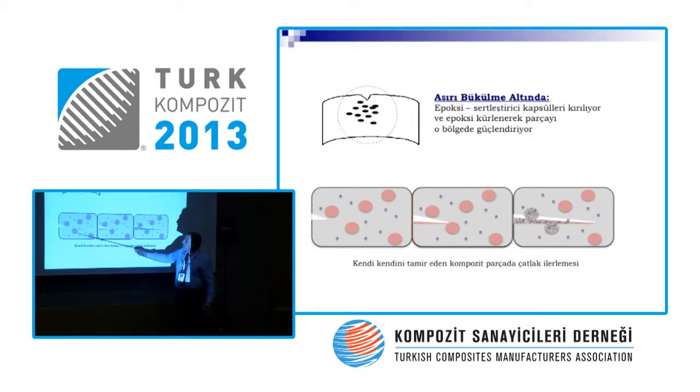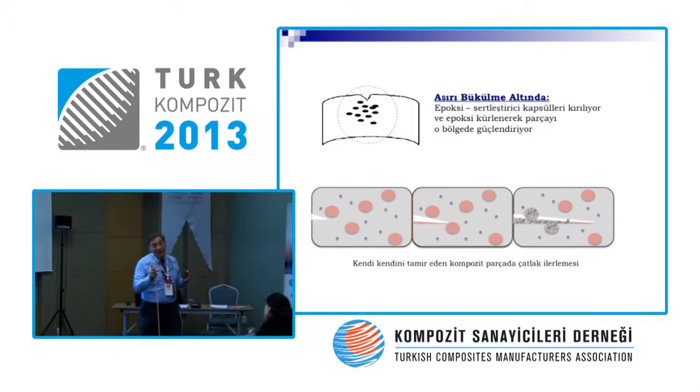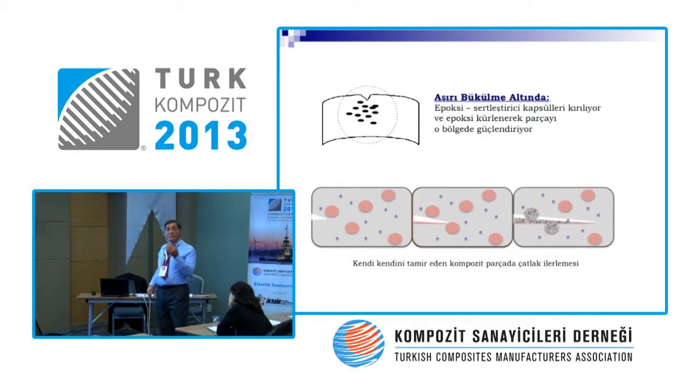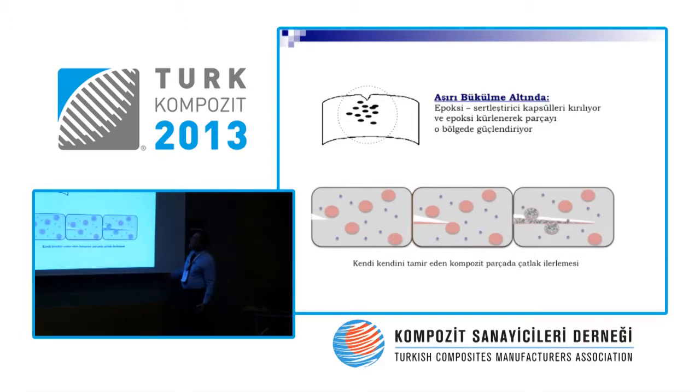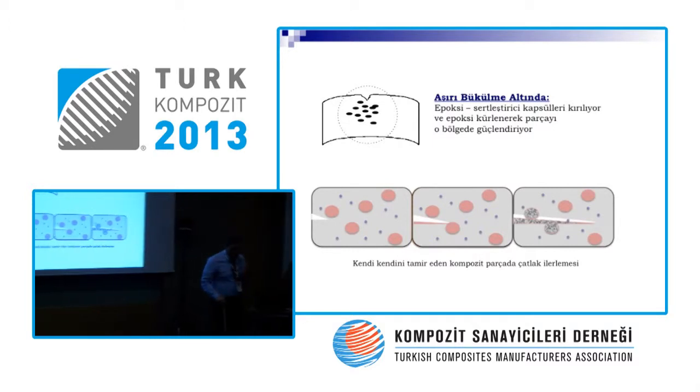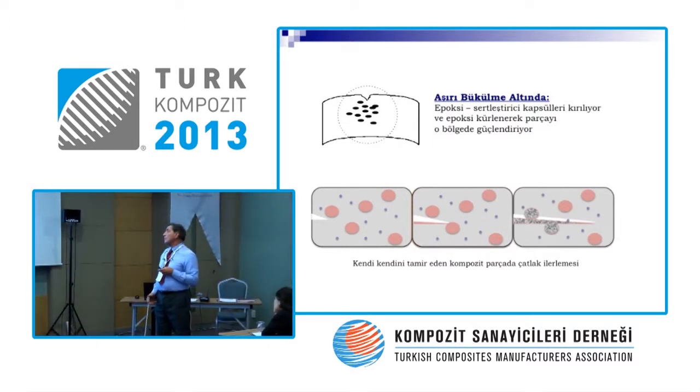And they have taken photos of these fractures, of these cracks. When the capsule is broken, the membrane is broken as well. They get out of the capsule, and in most of the cracked parts, the epoxy and the curing material mix, and in 3 minutes the epoxy is cured. It has low viscosity, and that's the reason why it is wetting the material and filling it, so it is a part that reheals or repairs itself. The mechanical resistance is, of course, lower than the original part, but it helps it work for a while.